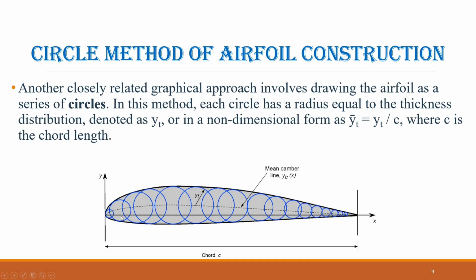The center of the circle is carefully positioned based on the desired leading edge radius, and the circle is then blended smoothly into the upper and lower surfaces of the airfoil. By plotting points along the circumference of the circle and connecting them with the rest of the airfoil profile, the designer creates a continuous, aerodynamic shape that satisfies both geometric and aerodynamic requirements.